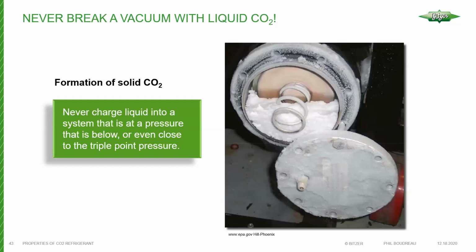If you were to expose liquid refrigerant to a system that is under a vacuum, you're really going to run into a problem quick, because you're going to start charging liquid into a vacuum, which will result in the immediate formation of dry ice. And at that point, everything is just going to lock up. And at this point in time, of course, you would never want to take a positive source of heat and warm that up and try and thaw that out. You're just going to end up getting into trouble.